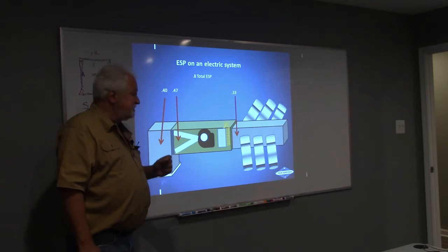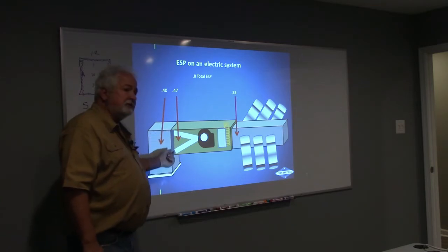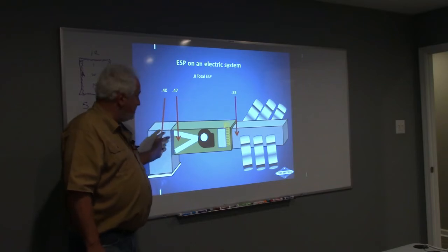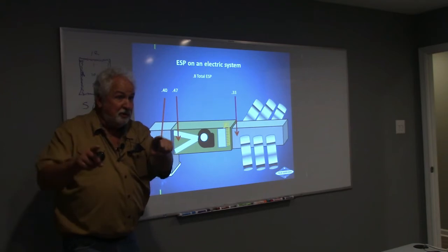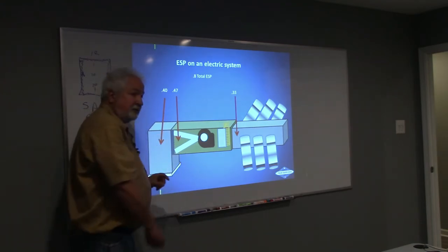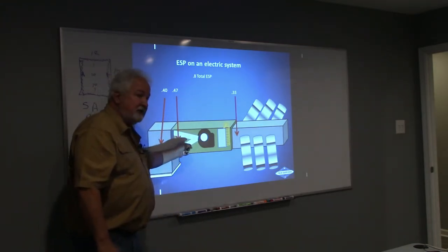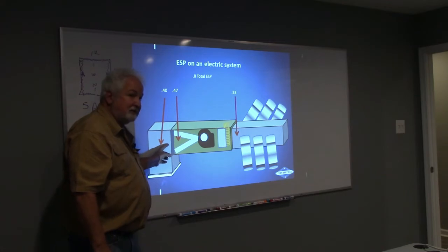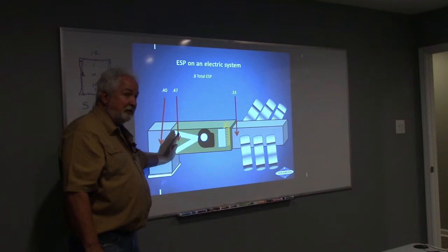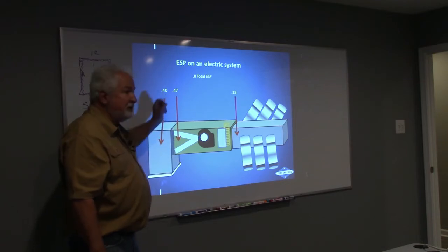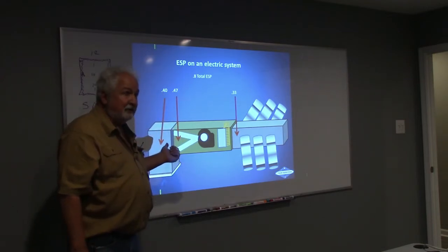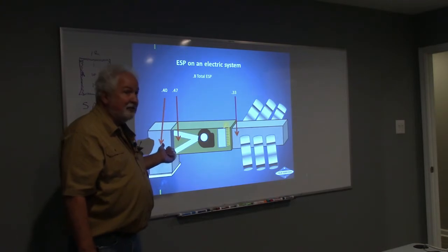So 0.07. Remember we were looking at those filters and I said 0.09 is probably a really good airflow filter. How's this one stack up right now? Because I'm measuring on both sides of this filter, I know how much the blower's sucking on this side, and I know how much the blower's having to suck on this side. So that's telling me the difference. I'm knowing exactly what that filter is pulling right there. Does that make sense? 0.07. Is that a good filter for airflow? I got virtually no drop at all on there. Does that make sense? Good.